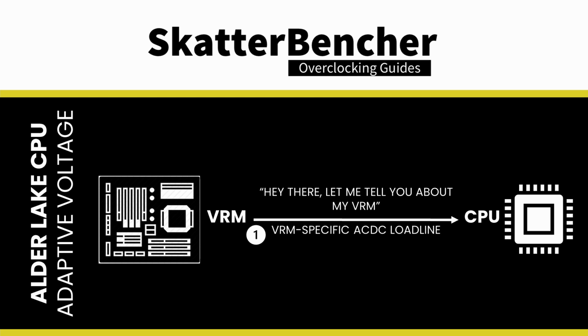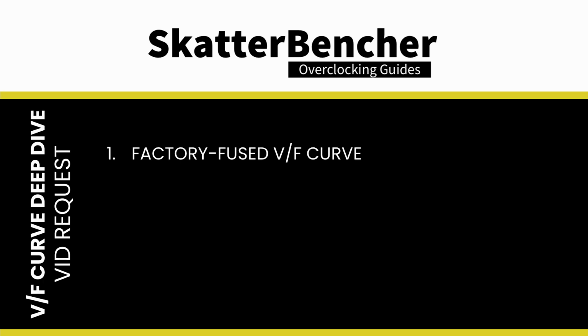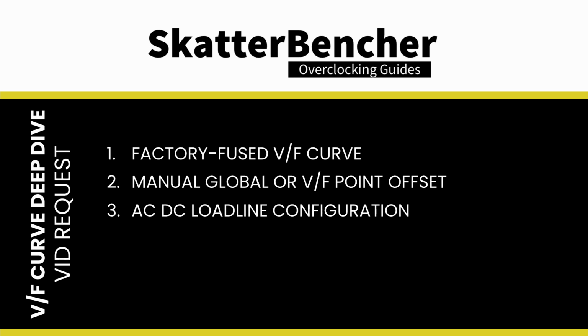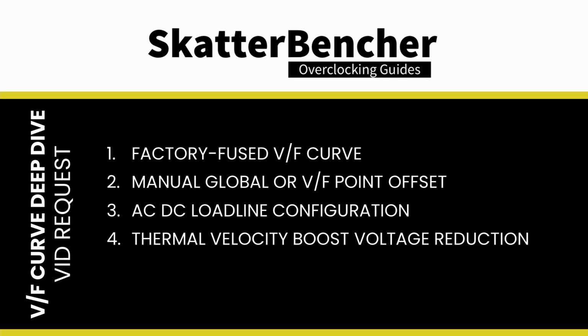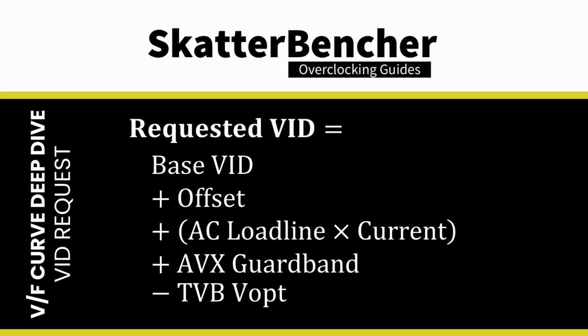With this information, the CPU can then determine whether it should request the voltage according to its VF curve or make any adjustments. In step 2, the CPU will issue a voltage request to the motherboard voltage controller using a VID. This VID is based on a variety of parameters, including the factory-fused voltage frequency curve, any manually set voltage offset or VF point offset, the AC-DC load line configuration, voltage reductions triggered by the thermal velocity boost technology, and voltage increases triggered by the AVX voltage guard band. For those who like equations, the requested VID can be expressed as follows.